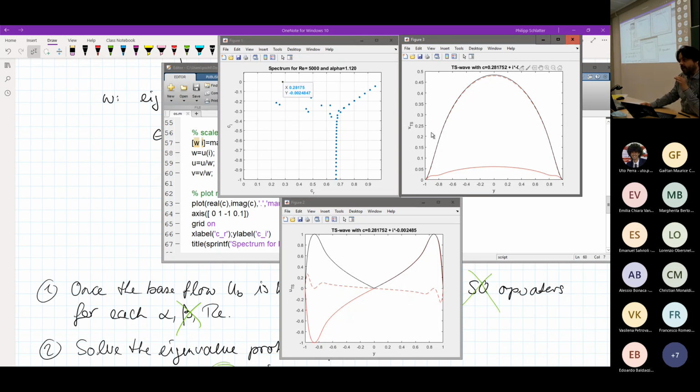So V is what I calculated for, and U is what I recovered using continuity. And what you see here in red is essentially that you have a high amplitude disturbance close to the lower wall, and also here with a negative sign close to the other wall. So that means you have a disturbance that has a wave-like character that has its maximum close to the 2 walls.